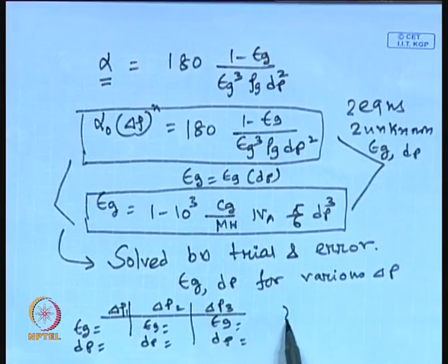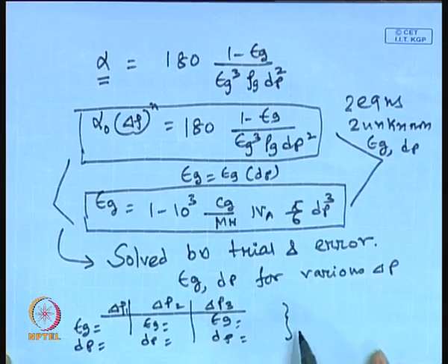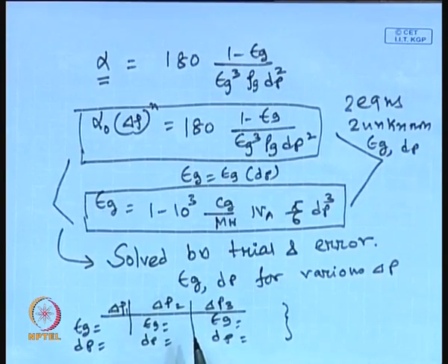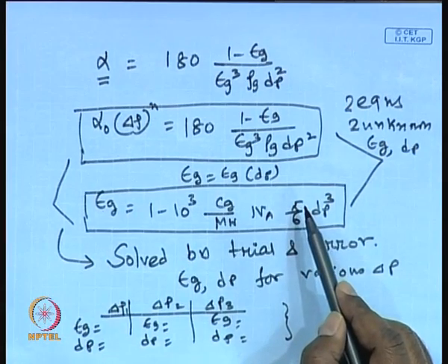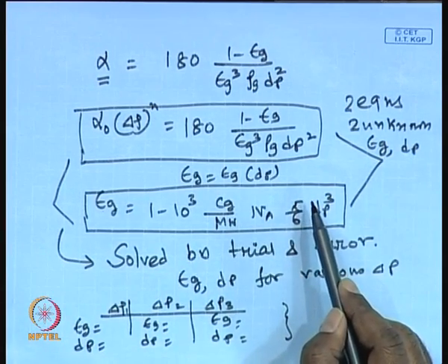Obviously, this method if you remember, this method is valid for the non-hard sphere solutes. That means, what I mean by that, suppose you are having a pectin gel and they are not hard sphere, right, they are polymeric. So, by changing the pressure, the gel will be compressed, the characteristic will be changed. Suppose the solute is fixed, that means the size will be fixed, but if it is a hard sphere, then we are not going to adopt this method. If they are hard sphere, we are not going to adopt this method, because in that case the particle diameter is fixed, the porosity will be fixed.